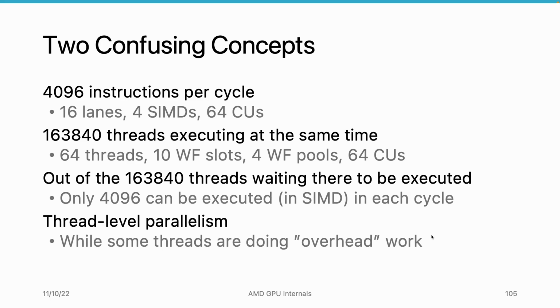So some threads may be working on fetching data to the compute unit, while other threads can start to work for the SIMD unit. And the number of 40 wavefronts that can be executed in one compute unit is generally a good match for the computational capability. Of course, this differs from workload to workload. Some workloads are more compute intensive, some workloads may be more memory intensive. For the most commonly executed workloads, such as matrix multiplication, we want to have a full utilization of the memory bandwidth and the SIMD computational power at the same time.